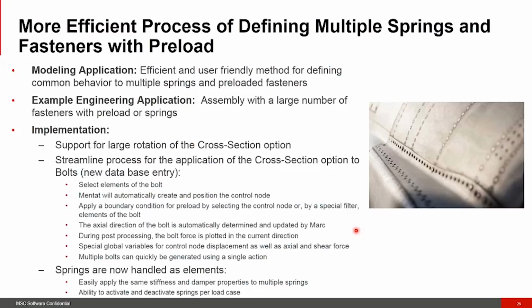In the implementation, the first thing we did is that previously we didn't really support large rotation and displacement for that cross-section option. So we've rectified that issue that you need for the preload of fasteners and bolts. And then we streamlined the process for actually defining that preload.